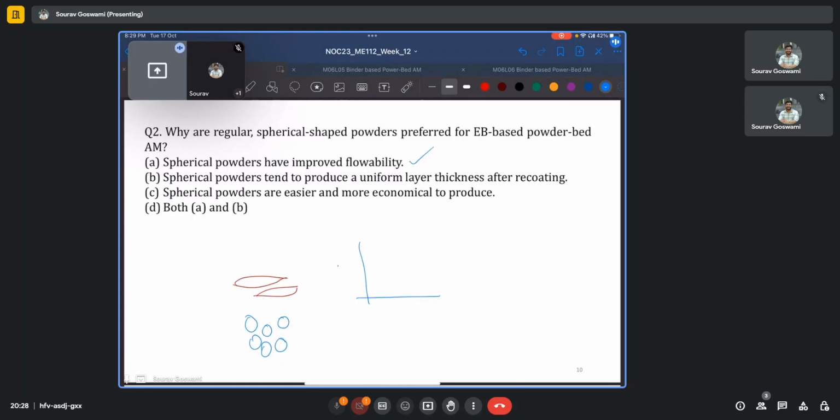So, in terms of the frequency or the number and the size of the particle, say the diameter, we will never have just particles of one size. What we'll always end up with is a distribution, and it is this entire distribution range that we utilize. Of course, it will have some mean particle size, but we need this entire distribution because to ensure good compaction and a uniform layer height, just having particles of one size won't do.